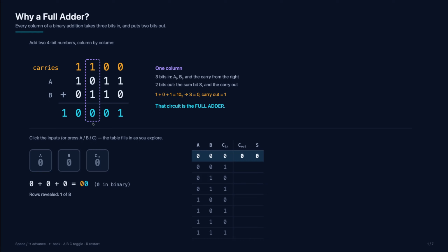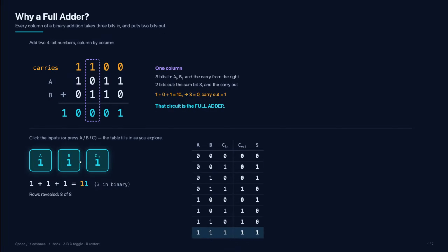All right, so the next thing we want to do is design a circuit. What makes sense to do is to come up with the truth table. So we look at all the input combinations. So what if I had a carry in? Then the sum would be a 1 with a carry out of 0 for this input combination. So we go through all the input combinations and fill out the rest of this table. I'm not doing them in the best order, but you get the idea. We now have the truth table.